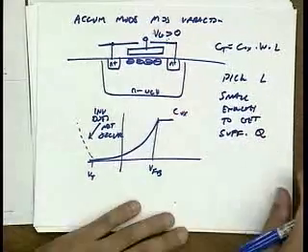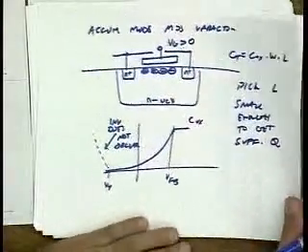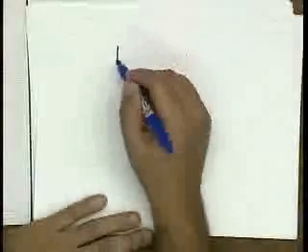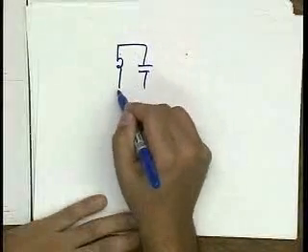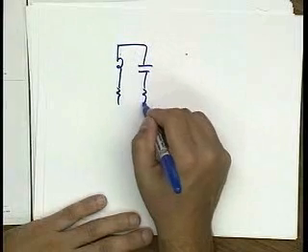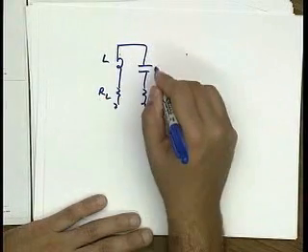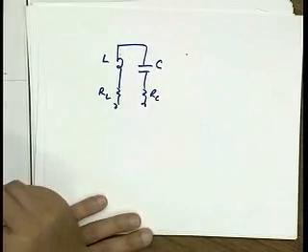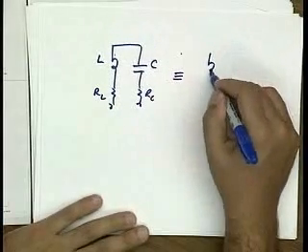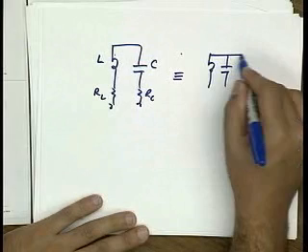And the reason that I say sufficient Q is remember that you're building a tank. So in a tank you have an inductor, you have a capacitor. This is L, this is RL, this is C, this is RC. We can convert this into a parallel LCR circuit.